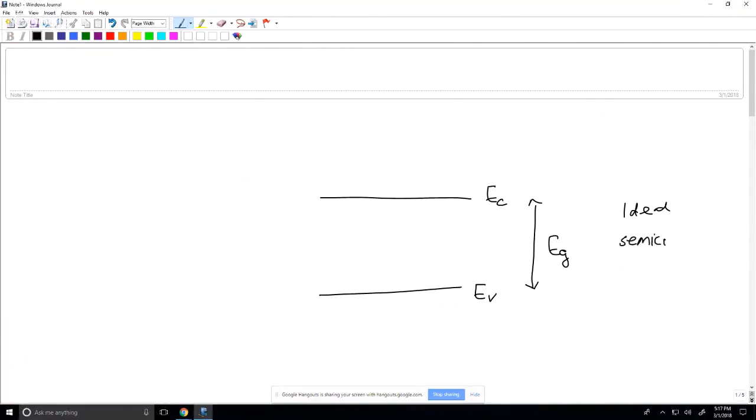But in reality, that is not true. Most of us work with semiconductor materials where, depending upon how we process them, there are always some defects in the material. For example, in our lab, we work on zinc oxide, and the way we process it always leads to defects. So how do we normally depict defect states? Defect states are usually of two types. We call one a shallow defect, and the other is a deep defect. Another word for defect states is trap states, so you can also call them shallow traps and deep traps.